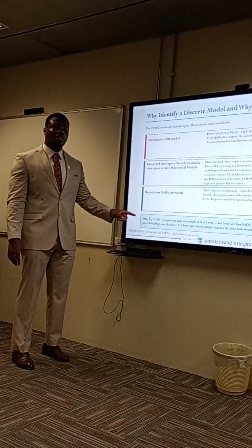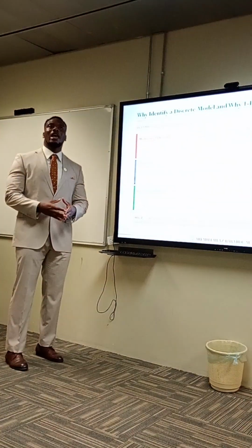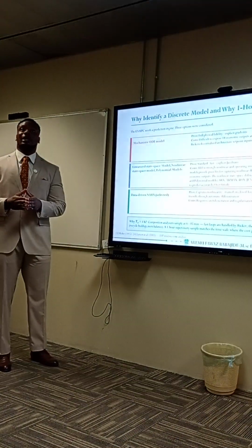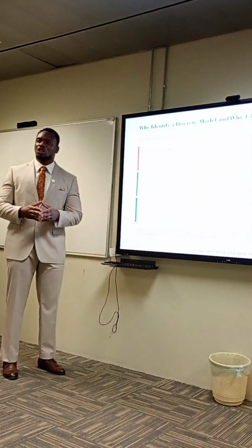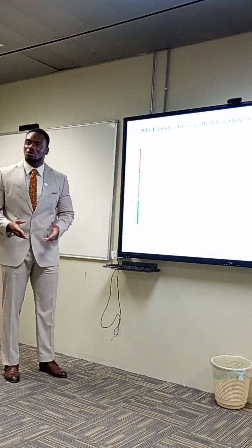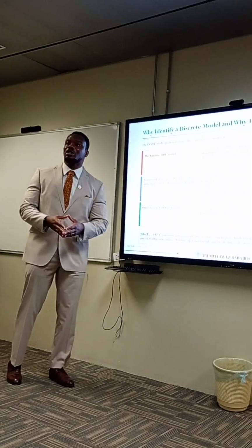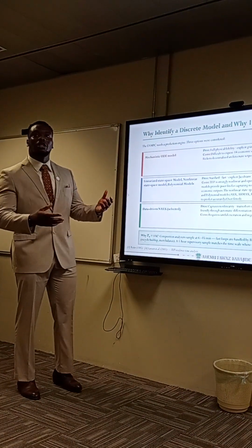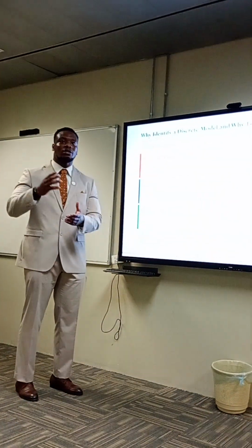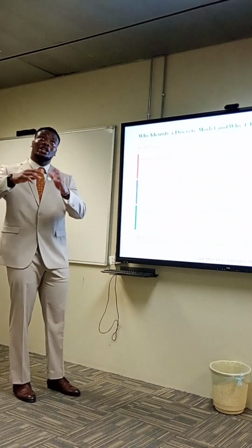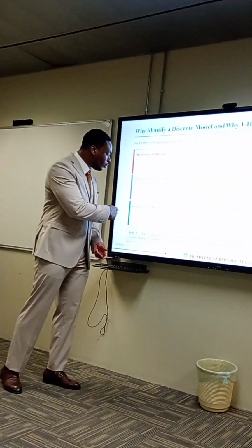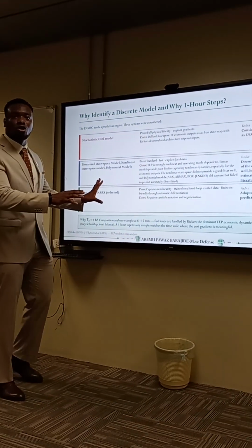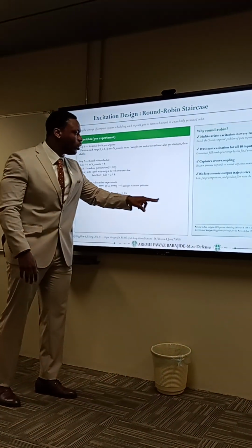Now we consider the sample time of 1 hour. Why? Because most processes in chemical engineering are very slow processes. It takes about 20 hours to settle. So if your process takes about 20 hours to settle, when you run the calculations, you would see the number of prediction horizon times the sample time is greater than or equal to the settling time. Calculations are not shown here, but they're in the report.